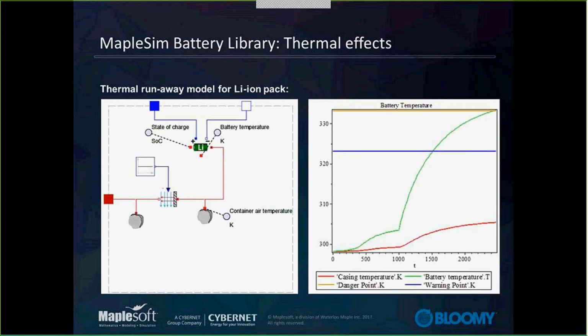When we put some of these concepts together as part of some approaches that are required for the battery management system, we can also expand the thermal management to include characteristics such as the container that the cell is sitting in, some cooling that might be available to the container with perhaps passive airflow over it, as well as any other chambers that the container might be encased in.